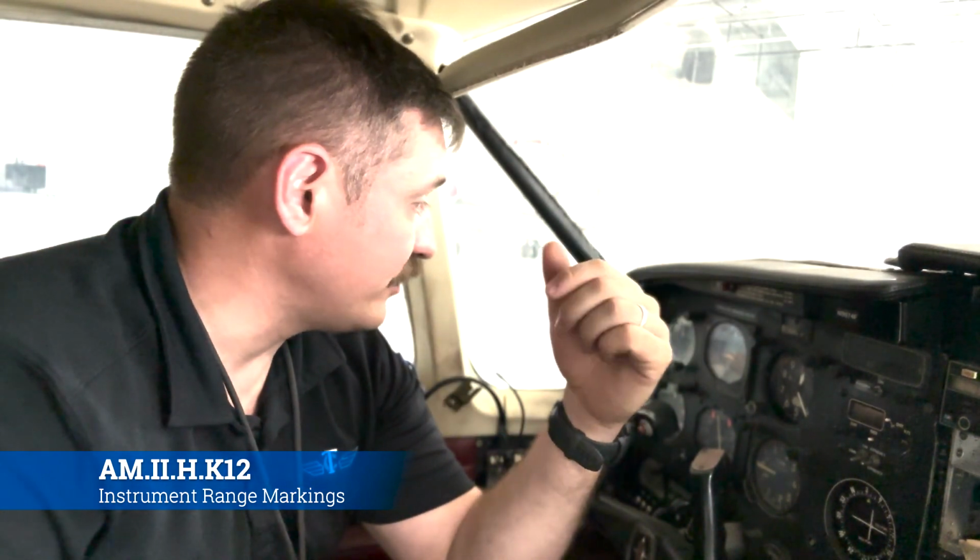Now beyond that, you'll end up having a yellow arc. That yellow arc will tell you, hey, look, this is kind of dangerous, because you're going so fast that if you hit a bump in turbulence or something, you could damage the airplane. And so you want to be cautious there. You generally don't want to live in the yellow arc. If you can pull it back and be inside the green arc, then you know that you're mathematically sound to operate the airplane beyond that.